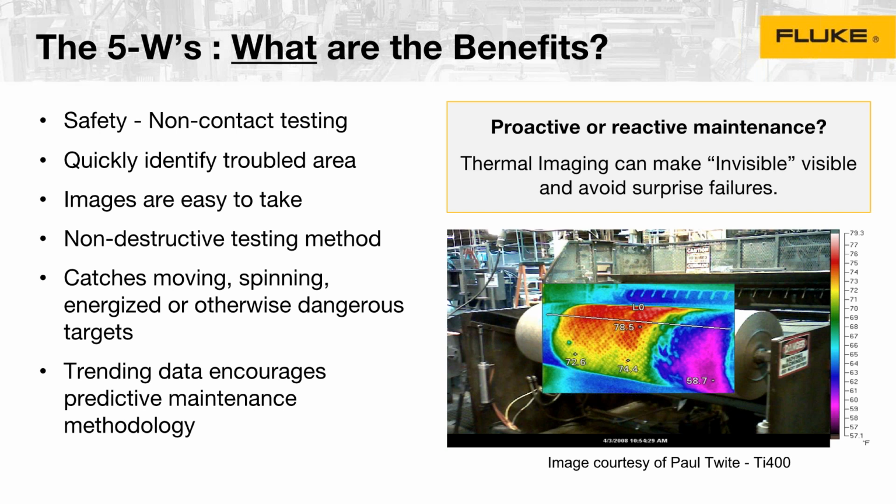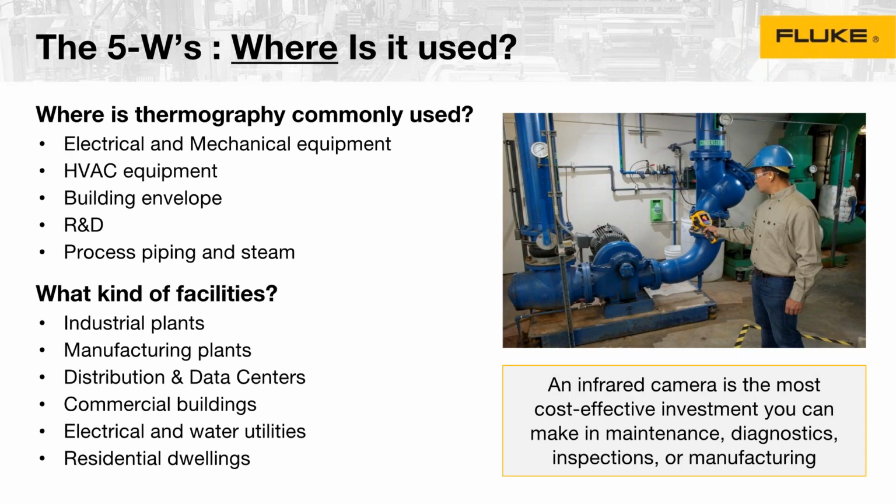It's really easy to take. It's point and shoot often. It's really non-destructive testing, so you don't have to change anything in your process. And then you can use some of the data for predictive and preventive maintenance methodology. Often we try to tell our customers, hey, start using this thermal camera, feel comfortable about taking some of the pictures, and then include this into your proactive maintenance program. And I think that will help you to move forward.